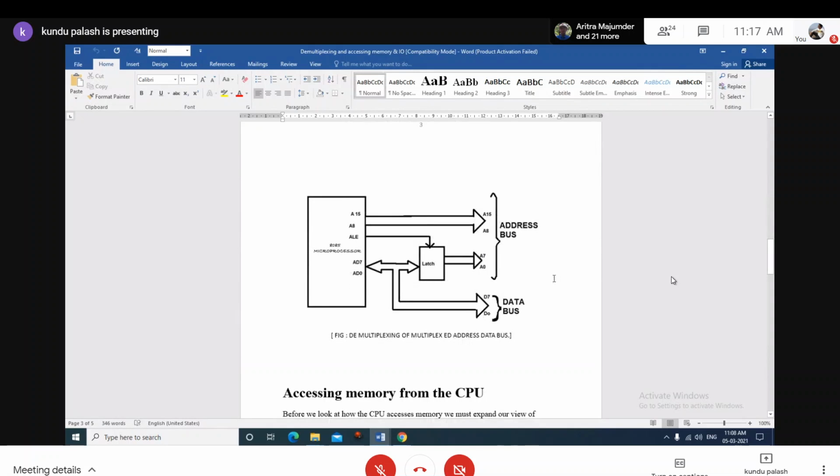Now, what is the address and data bus interfacing with respect to the memory? We know the 8085 can produce higher order address signals over the A8 to A15 lines, and the lower order address signals, which are mixed with the data signals, the 8-bit data signal designated as AD0 to AD7. That means the lower order address lines and the data signals are combined, and have meaning at different time slots, on the same bus.